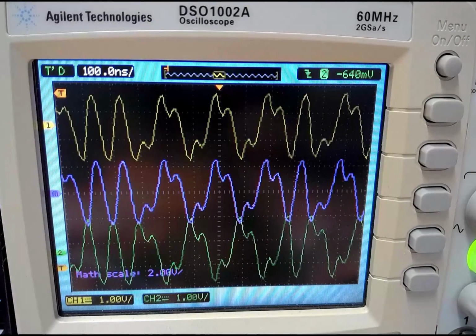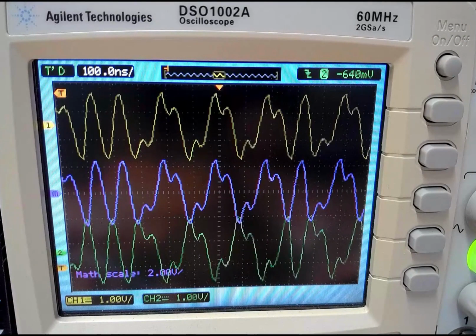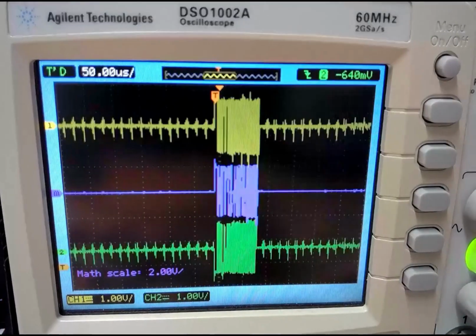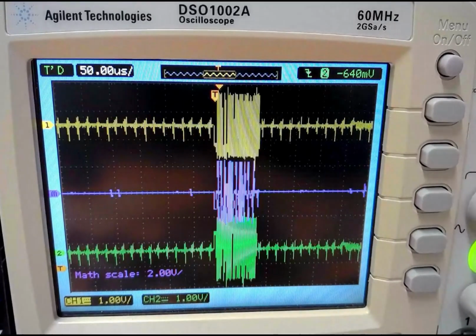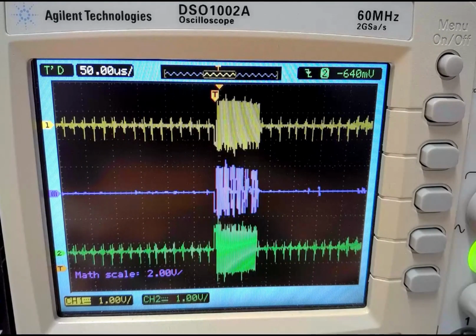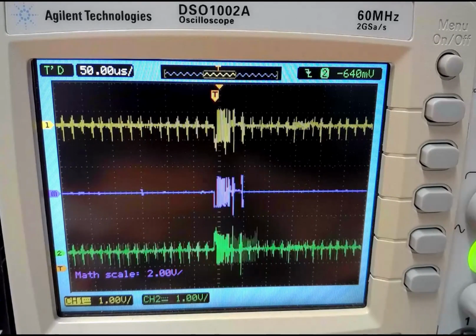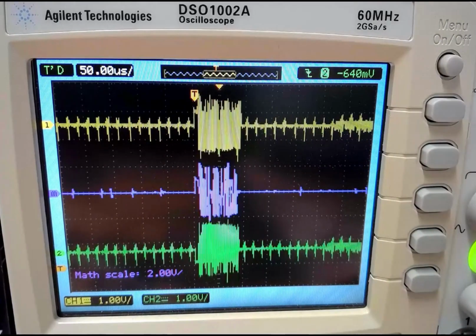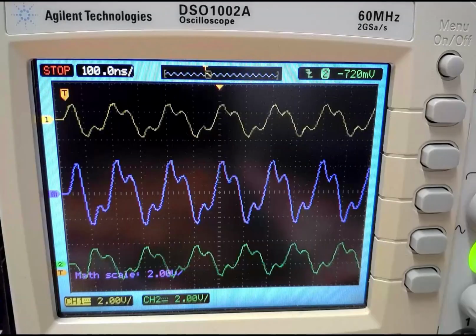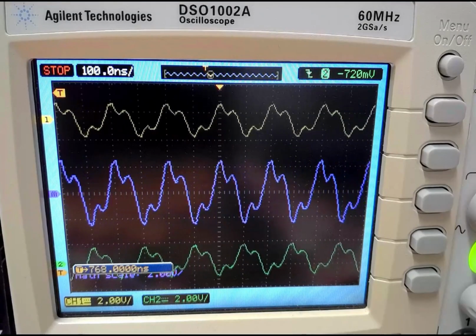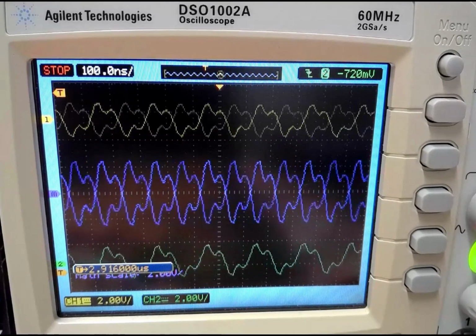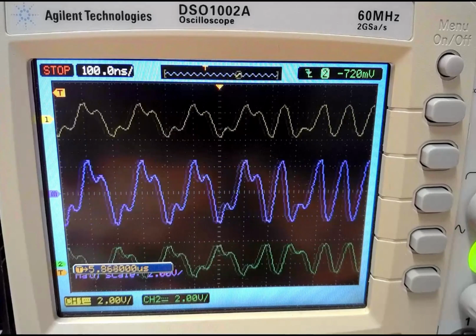Then when I plug in Pi 3, you can see our signals starting to come through here. Again, a little bit noisy, but if we zoom out a bit, we can see there is our packet of data. A bit of aliasing on the signal there because we're zoomed out quite a lot. So that's why it's all jumping around a bit. But that is our ping packet data coming in. Again, we can zoom in a little bit and start to analyze what this series of squiggles is actually transmitting. What data do these signals represent?